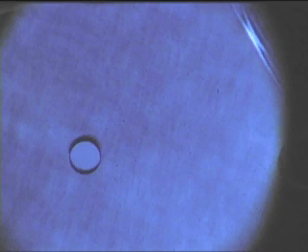The beam was directed at the 6 mm diameter hole, and the delay increased to observe the interactions. At about 3.8 microseconds after the element has been pulsed, the mechanical pulse enters the glass from the wedge. The incident angle is greater than the first critical angle, so only a shear mode is present in the glass. After entering the glass and moving about halfway towards the hole, the pulse image is approximately 5.3 microsecond delay from the entry point. As the delay is increased, we see the pulse maintaining an almost plane wavefront that narrows slightly as the target is approached.